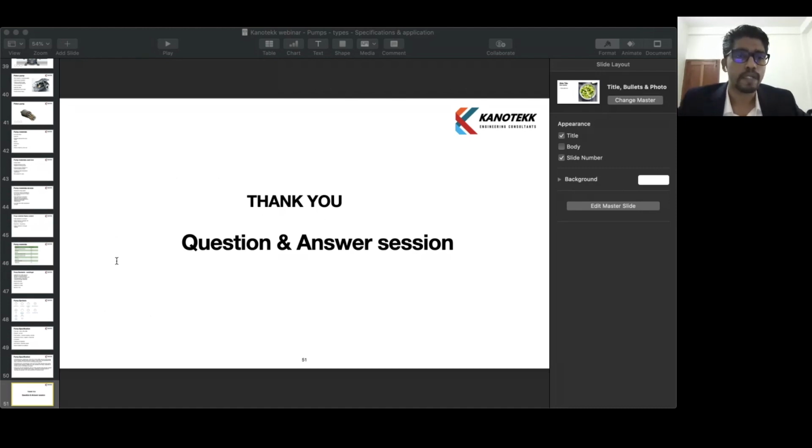Okay, in a certain project the NPSH available is very low and the margin is also very small, 0.1 or 0.3. Is it okay to specify 0.3 meter? It is okay. In some cases we go for a tighter margin, but it is advised to keep at least 0.5 meter margin. 0.3 is acceptable. Theoretically, it is acceptable. Even practically, it will work fine.